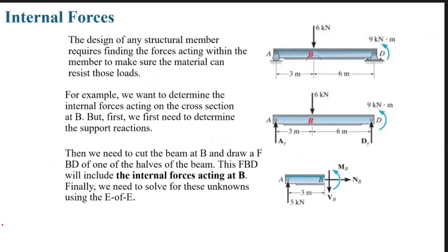Okay, internal forces. Before you size or select any material, the very first step is to determine the shear force and bending moment diagrams. These diagrams tell us where the beam experiences the highest stress, so you can design for both strength and economy. What's the meaning? It means first we should find the shear force diagram.